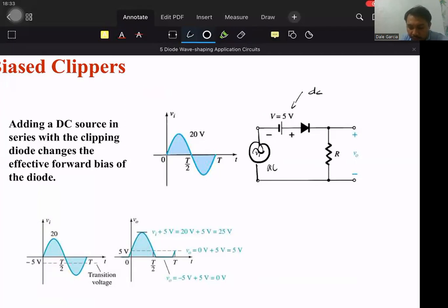So what does that do? In this particular case, it increases, no? It increases. So if we do KVL here, there's no other way to explain what's happening here but to use KVL. If we do KVL in that direction, no need for the other half cycle because it clips away directly. In the positive half cycle, not only does it pass through, but it adds plus 5 volts.